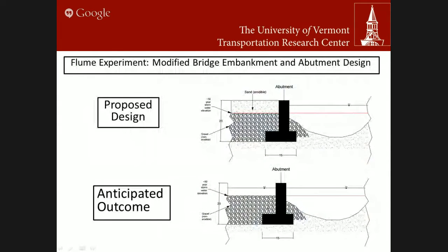So then I worked on proposing a design with creating this fuse. So how would we create this fuse? My thought process was you wouldn't design the fuse to erode away during low flow events, just normal little storms, where you wouldn't want the embankment to blow out before the bridge does, but only during a storm event that you would consider dangerous.